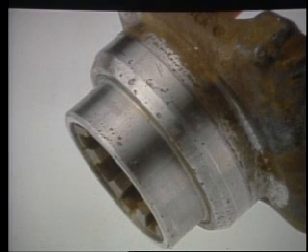The seal surface of the yoke should not be rusted, burred, or nicked. Any of these imperfections will damage the seal. Leakage can also occur if the yoke is painted after it is installed on the transmission. Paint chips can quickly wear an otherwise good seal.